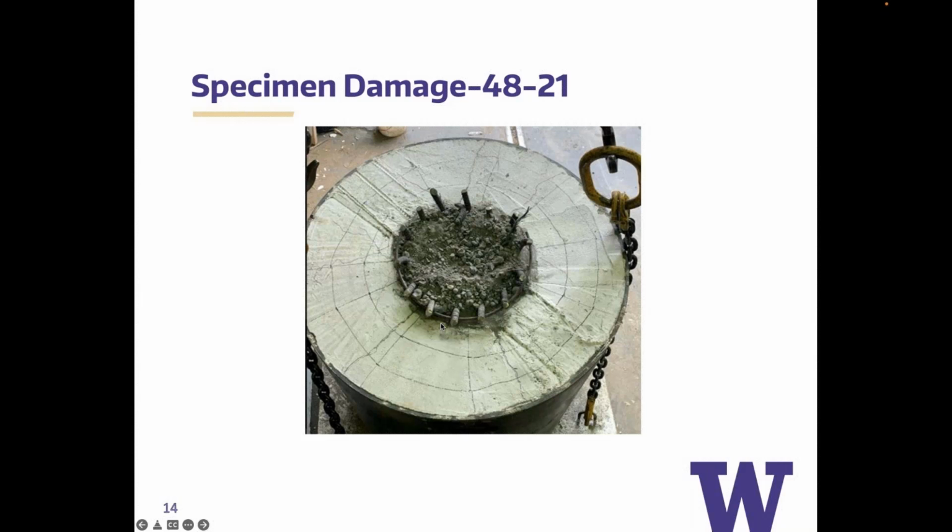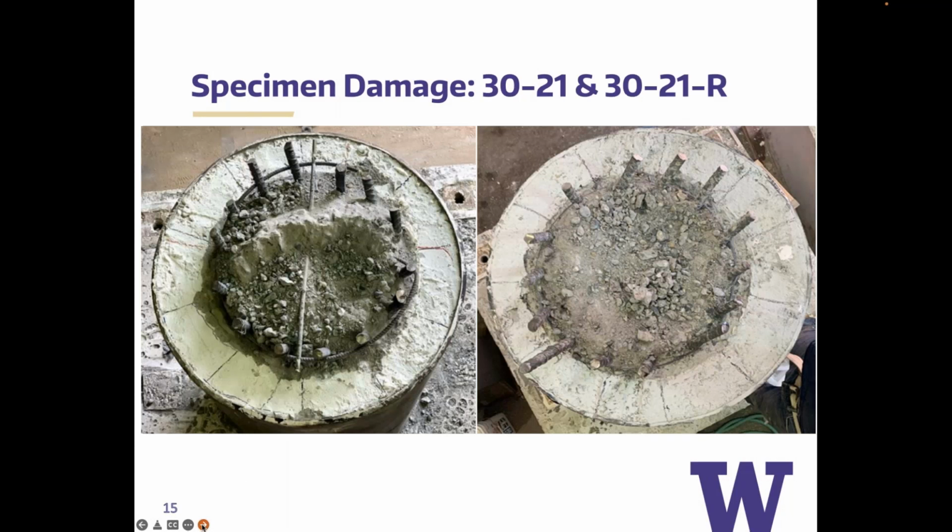So the concrete between the edge of the reinforcing bar to the interior of the steel tube. And you do see a little bit of damage around those bars, because although it's subtle, if you look back to column foundation connections, other connections, you will see that it's pretty common to have pretty severe bond damage. Kind of goes to what Professor Thonstadt was talking about.